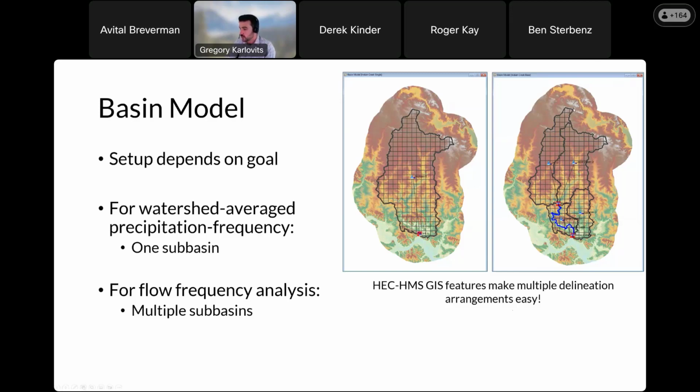When you run these simulations, if I run an average of 10 events per year, say for the first year, event number 2 causes the annual maximum here, but event number 8 causes the annual maximum down here, that's okay. That's the beauty of these sorts of things, because a different storm event is likely to cause a big flood here for the whole watershed as opposed to just up here.